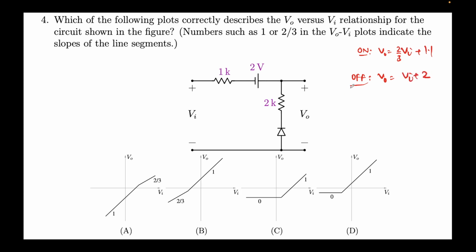Okay, again we'll just analyze, let's say we apply a very large negative bias to this. This means this is at higher potential, let's say plus 10 volts, and this is 0. So we can see this has chances of becoming forward biased, and current will start to flow. So when we put a large negative Vi, this diode will start to conduct.